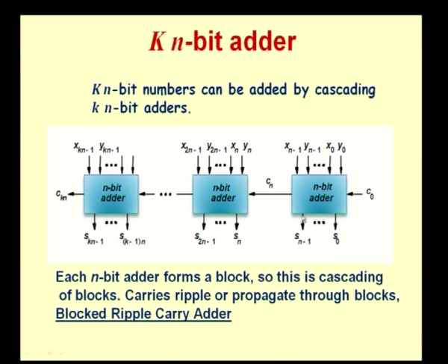This is, you can look at this as first digit, second digit, third digit, and so on. So, if one digit requires n bits to be represented, I am talking about now k such digits being represented. Okay. So, each digit is handled by means of an n bit adder that we have here. Okay. So, you can see what we are able to achieve by doing this kind of cascading of these adders. So, by cascading these adders, you can now construct larger and larger adders. So, that is the advantage we get with this kind of circuit design.